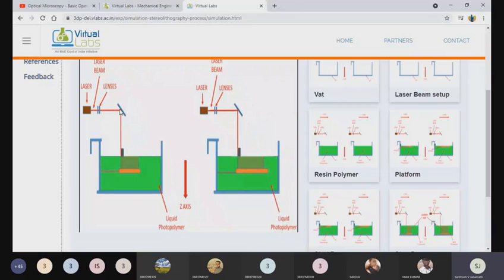This is the laser beam. This is the blade, or doctor blade. This will maintain the thickness of the polymer resin. As the platform moves down, the amount of liquid will come up. Hence, this is exposed to the laser. The laser traces only the required area, the required cross section. It will not trace unevenly.